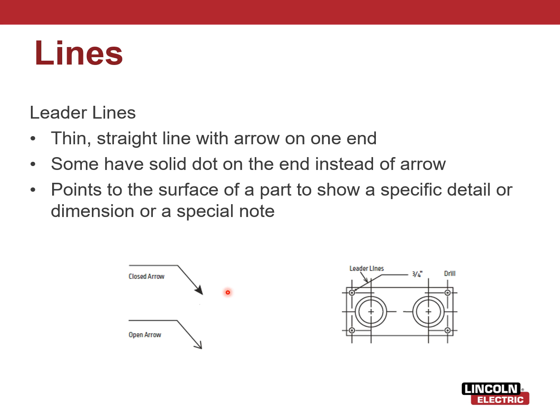So this can be a few different things. This is telling us that's a 3/4 inch hole. You could also use this if you wanted to denote drill to something specific. So this is for a detail or a note, so a little more vague.